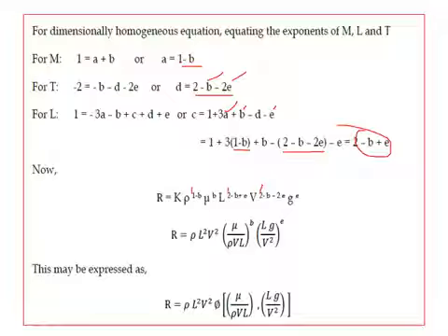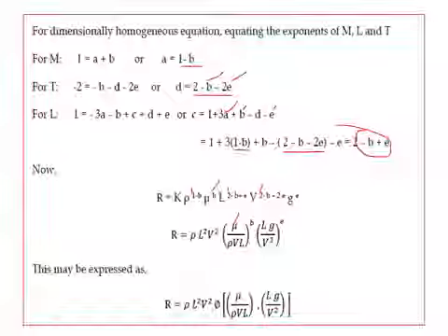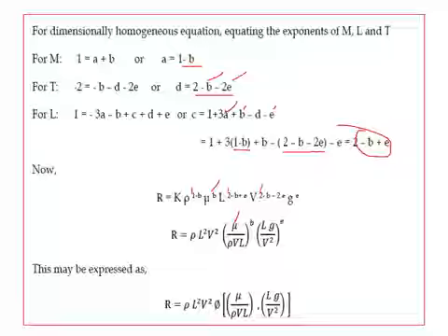Similarly we can write for the like powers of B. So this is mu to the power of B, the rho comes down here, V to the power of minus B, so V comes here. Then next L to the power of minus B, so that means another term with the like power B is mu by rho VL.